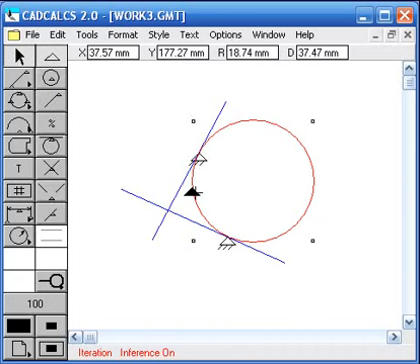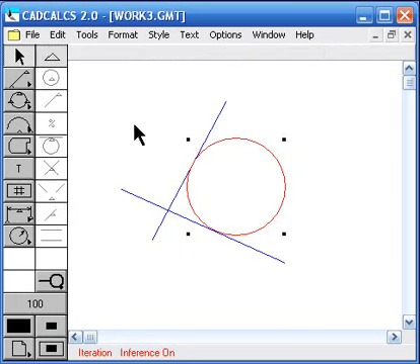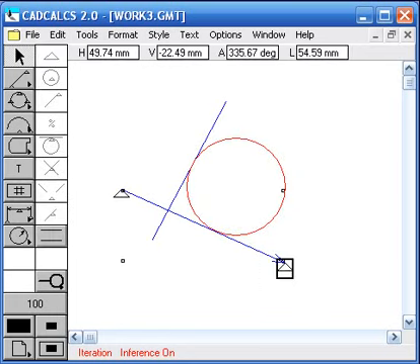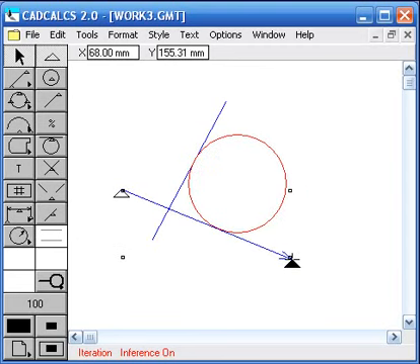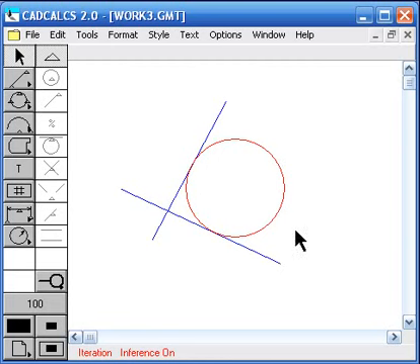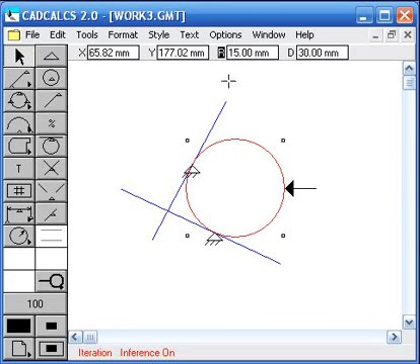But I could give this a radius constraint. Let's say we make it a 15 millimeter circle by entering 15 in the value bar. And now you'll see the behavior of the circle will be a little different. If I change this, the circle is maintaining its radius while maintaining the tangencies also. So these are the 3 options for creating circles, and you have the flexibility of assigning radius constraints or many of these constraints using the formula bar.